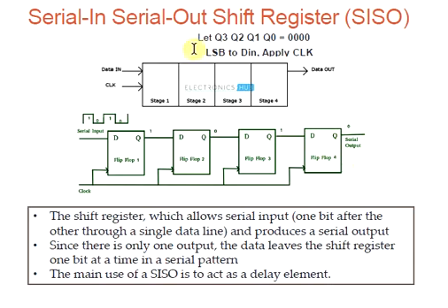Here you can see that for the first clock pulse, the least significant bit of the information will be given to the data input. This will be transmitted to the second stage for the next clock pulse. At that time the second digit will be given to D in, and for the next clock pulse the third digit will be given to D in, and simultaneously these numbers will be shifted.